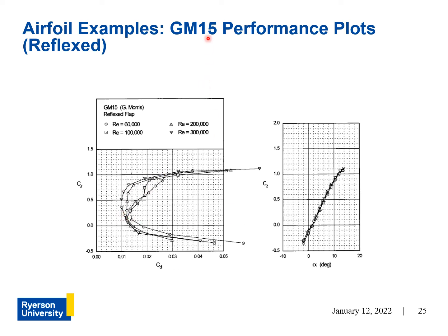So like the MA409 airfoil, the GM15 in its reflex configuration, when it has minimal camber, has better climb performance for the same reasons as the MA409 airfoil. And likewise, the GM15 in its unflapped or cambered configuration performs more like the A18, where it has better glide performance.